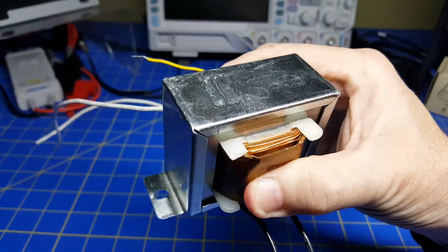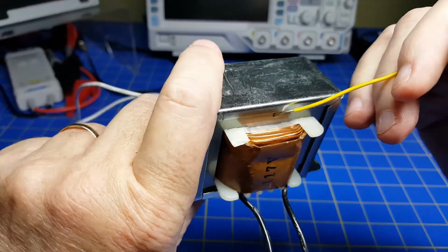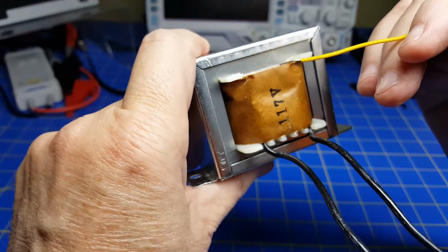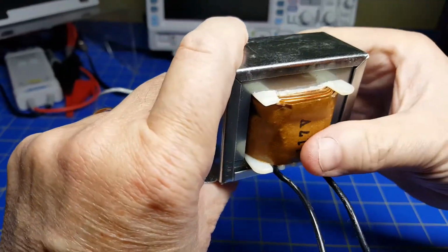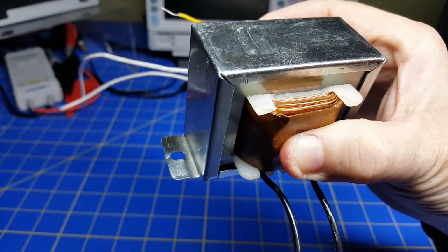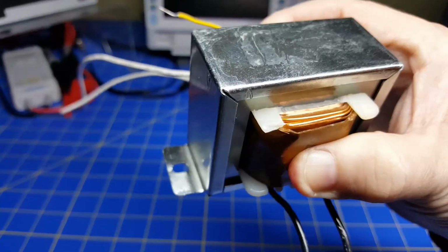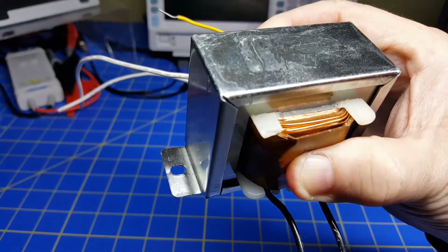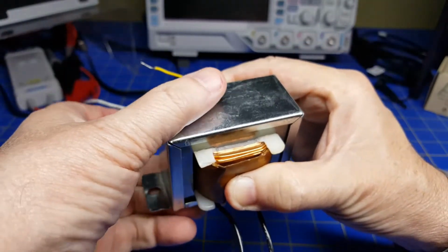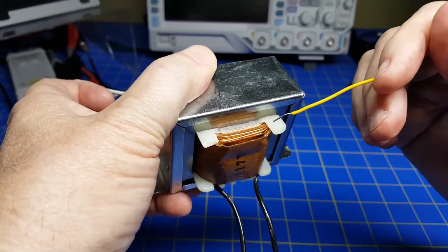Now you can see there's a lot of turns on this transformer, okay? For the 120 volt, I can see 5 turns right away. And if you multiply that times this length of winding, there's a lot of turns here. So we know right off the bat, we're going to have to think about things like resistance. Even though it's just wire, there's a lot of turns, so there's going to be some resistance. And there's going to be probably a lot more resistance with the 120 volt winding because it's smaller wire, and probably a lot more turns.